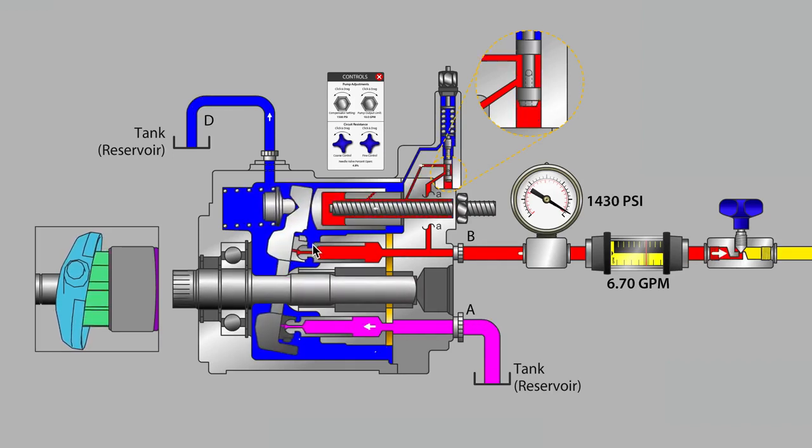All of those clearances, and in some languages when you read the notes for a piston pump, they literally refer to this fluid in a word that translates to leakage oil. We're not necessarily talking about bad leakage, but it is internal leakage between components that have a clearance. That fluid together with controller exhaust comes together, and all of that is present on the case drain line.